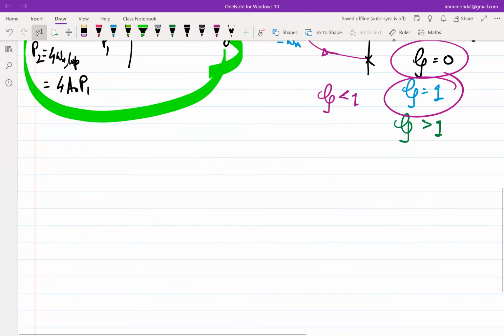Okay. So now one might say, what's the big deal? I can write out the polynomial of the closed loop system and try to figure out the pole locations. That is doable, but that is severely limited because for anything higher than third order you don't have a generic solution for finding the roots of a polynomial, right? And if there are no generic analytical solutions, forget about developing an intuition. That's not going to happen.